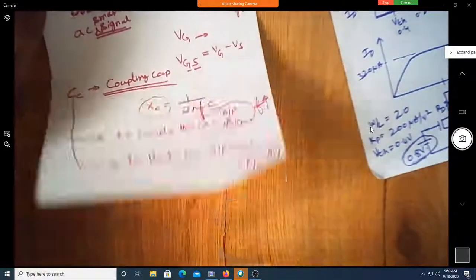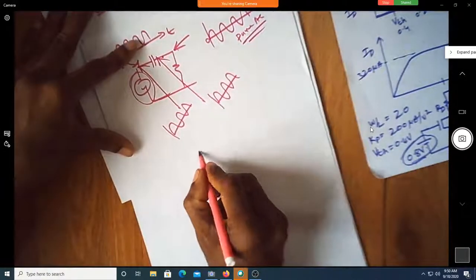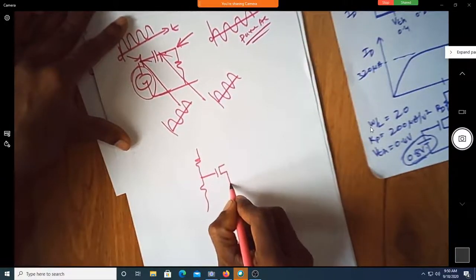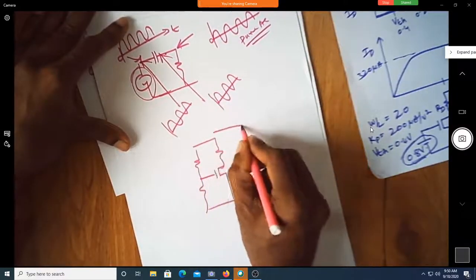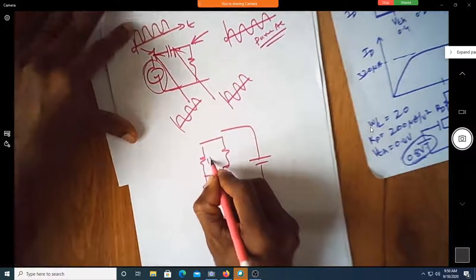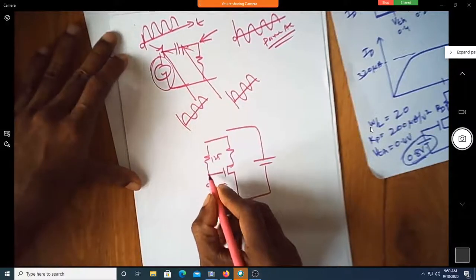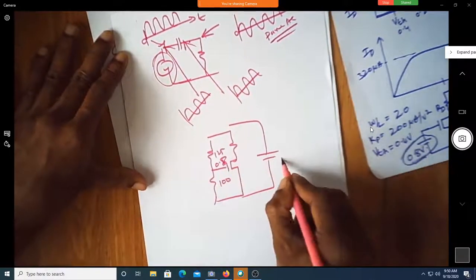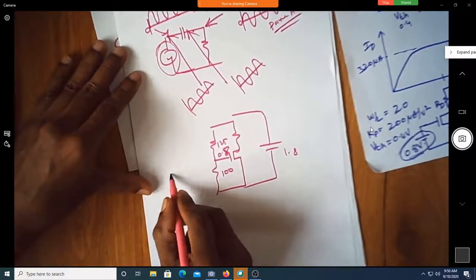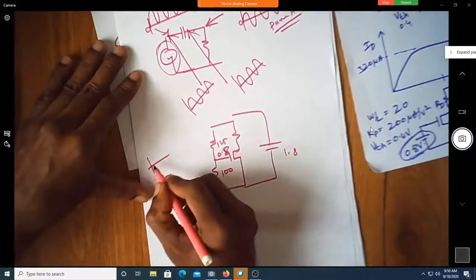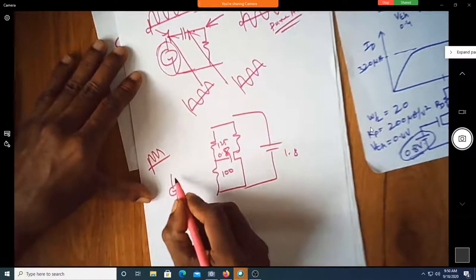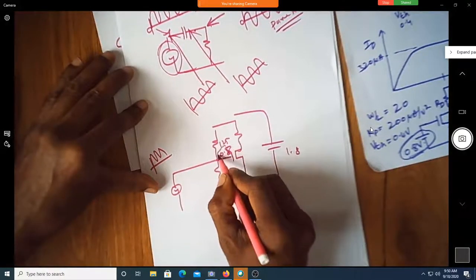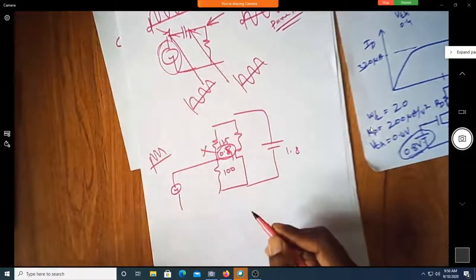It will combine. You have designed a resistor network, so you did so and so, correct? So this is 125K, this is 100K, now it is 0.8 volt, correct? Now assume that you have a source which has got some DC component. The moment you connect this to this, this is no more 0.8. Why is it no more 0.8?